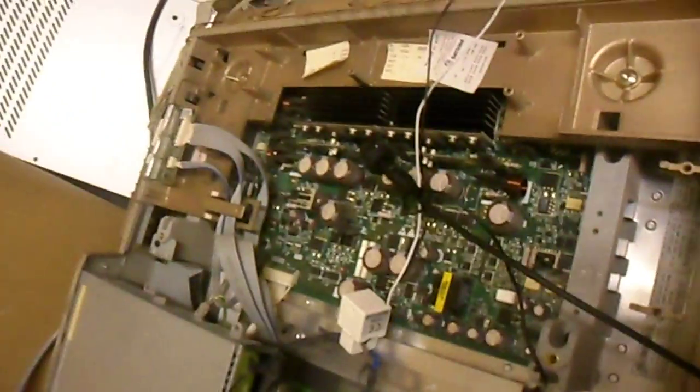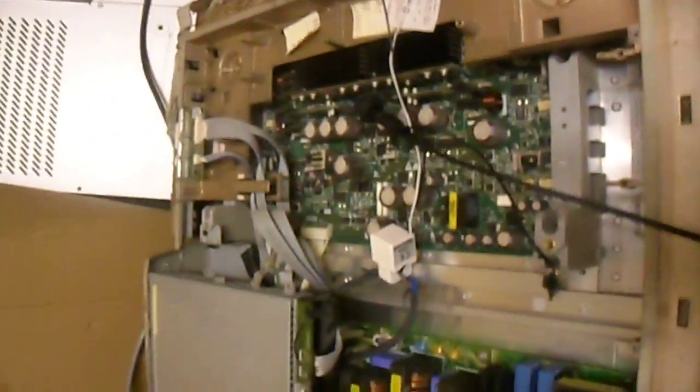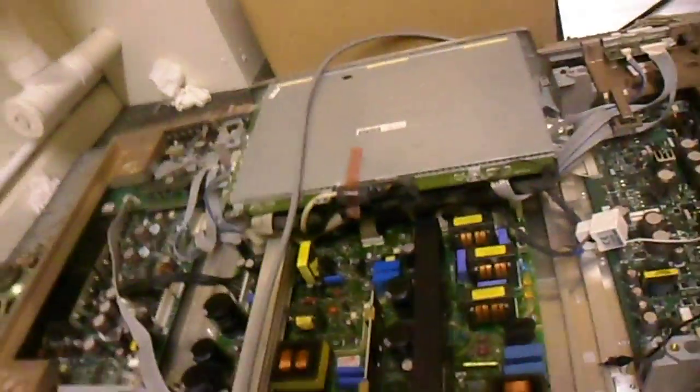So that's a little digression on how a plasma panel works. Enjoy the engineering porn here, because look at that. Jeez, a lot of power electronics on there. This thing is dealing with 100 volts at about 2 amps. Well, each side deals with about 100 volts, 2 amps. It's very good construction. You've got United Chemi-Con capacitors throughout. The power supply is Philips. Now this is the faulty part, but it's got Rubycon and Nichicon capacitors throughout it. The build quality is very good.